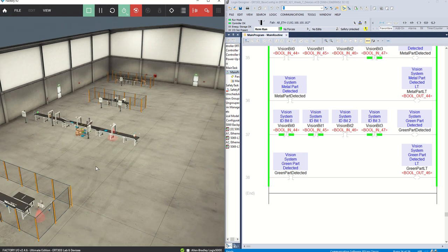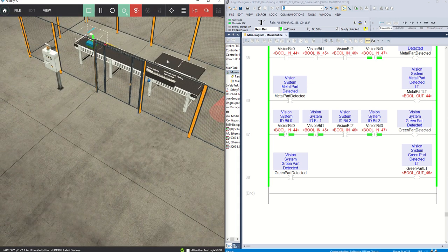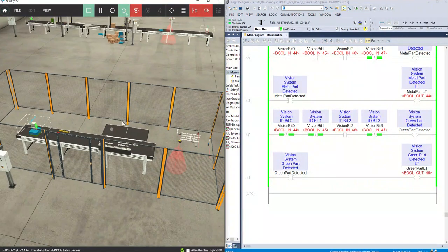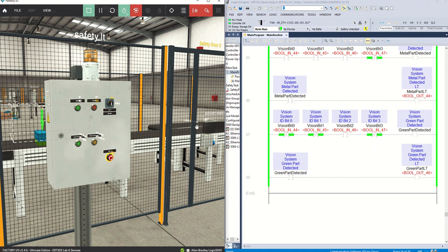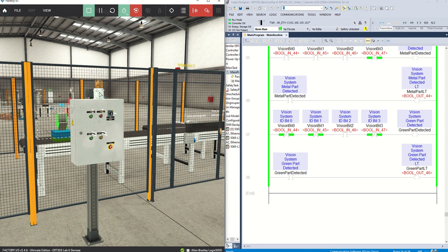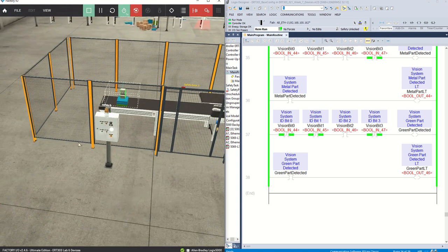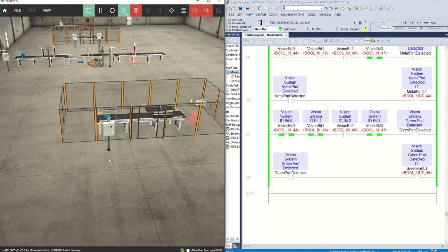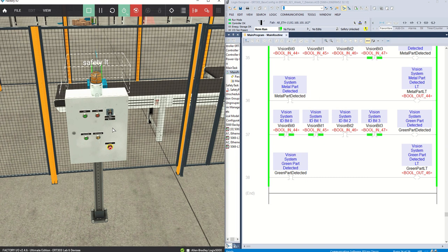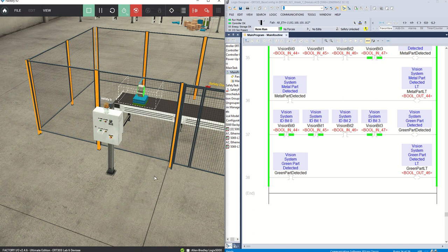So now what are you actually going to program? Here is the machine you are going to program. We have 2 conveyors here, and we have a panel. What I want you to do is make the conveyor run like all the other conveyor systems run. You've got an e-stop, a safety door, a light for safety, start and stop buttons, and auto/manual. We should be able to jog that conveyor as well. And then we have a pivot arm here and some buttons to control that pivot arm. And what we want to do is automatically sort green and blue parts.